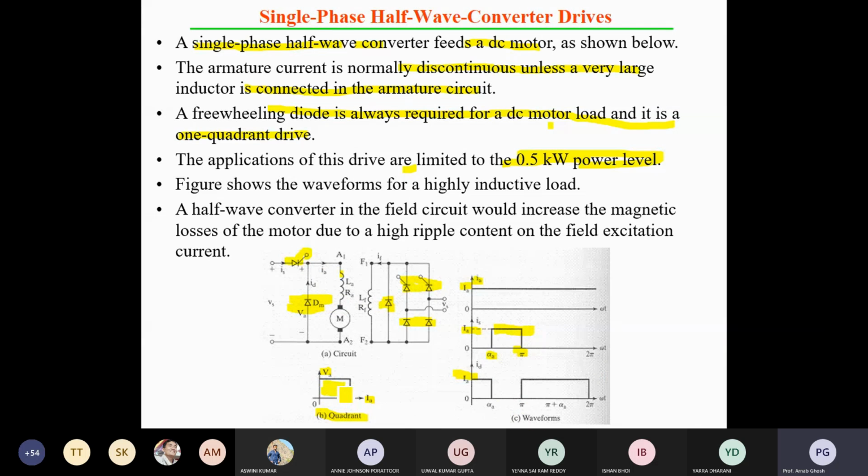In Fourier analysis, the fundamental is sinusoidal, 50 Hz for the fixed system. A square wave inherently generates harmonics, but in the motor the inductance of the armature winding and field winding can act as a filter, so an additional filter is not required. Both workings will be there.